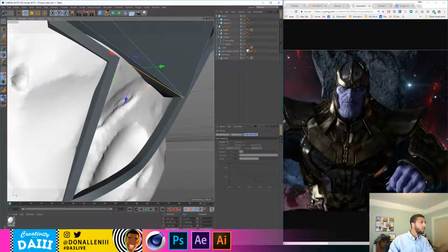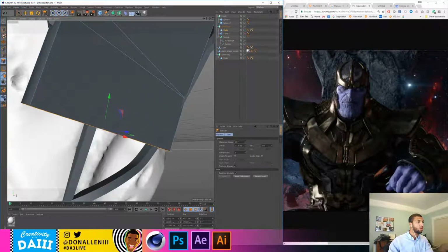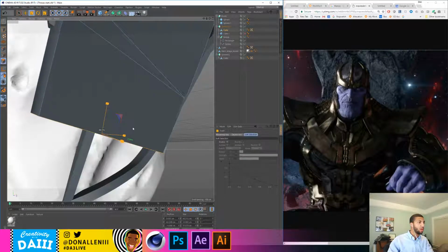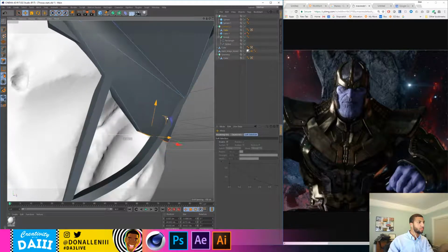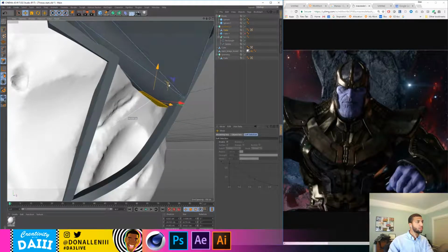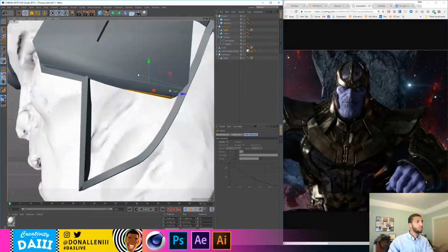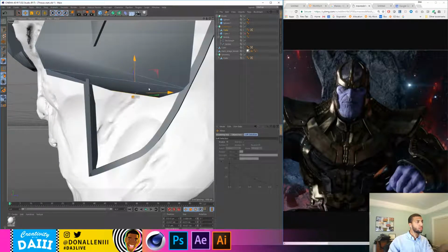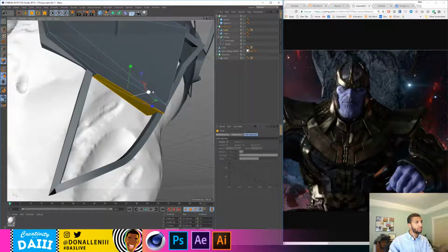All right, we can take the faces here and extrude them downwards. So we can do MT to extrude shortcut. We'll kind of extrude those down and then scale them down and then move them. And then I'll even scale this one up.